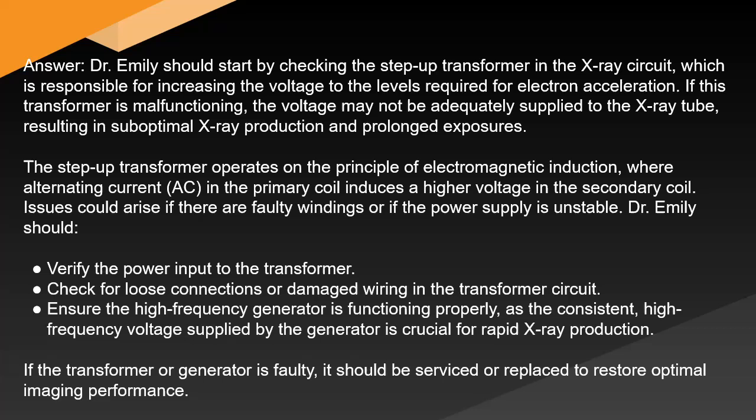Dr. Emily should verify the power input to the transformer, check for loose connections or damaged wiring in the transformer circuit, and ensure the high-frequency generator is functioning properly, as the consistent high-frequency voltage supplied by the generator is crucial for rapid X-ray production. If the transformer or generator is faulty, it should be serviced or replaced to restore optimal imaging performance.